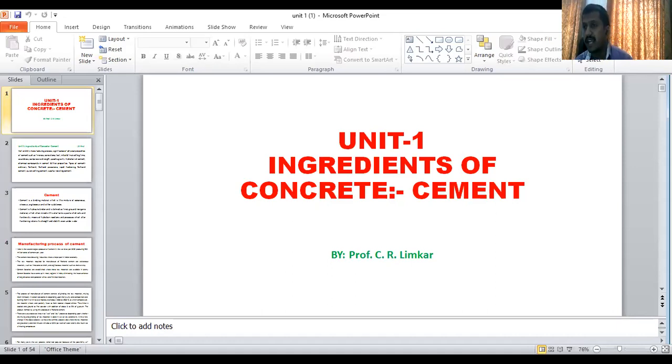And after that, we have started discussion on what is meant by the word soundness of the cement, and what is its significance. Let us have some brush up of our yesterday session. What is soundness? Soundness is going to get created in a cement when there is presence of excess lime and magnesia. Whenever there is presence of excess lime content in your given cement, it leads to soundness. Soundness leads to the change in the volume of that particular concrete.